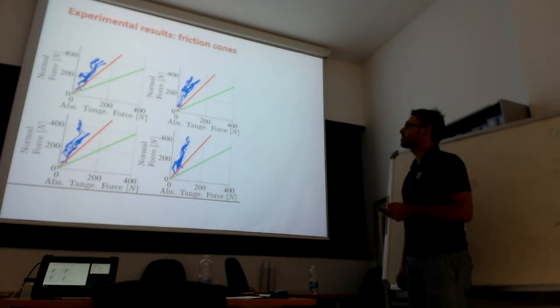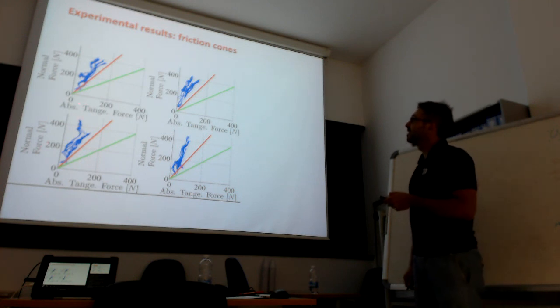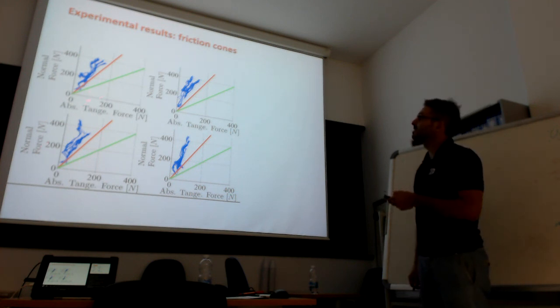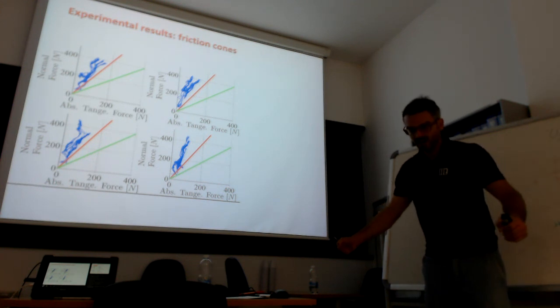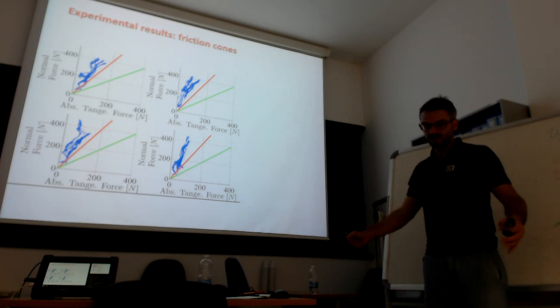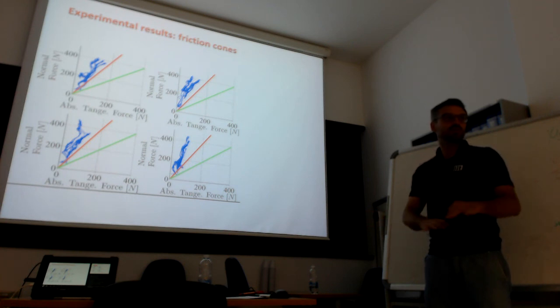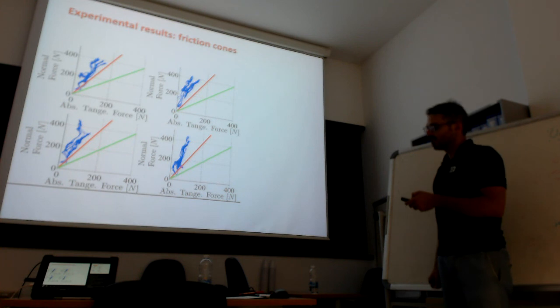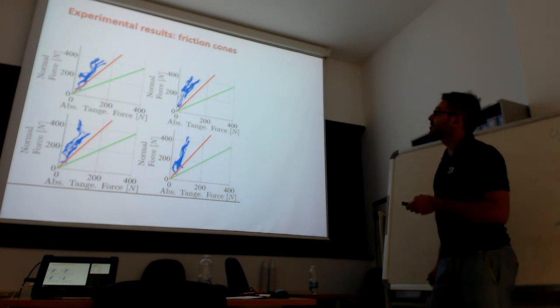And these are some experimental results that I obtained with those experiments. We see here the estimated friction coefficient. We did a very simple test applying tangential forces on that surface until the robot starts to slip, and measured the point at which they lose the contact, which was the tangential force, and we found out that there was a friction coefficient of